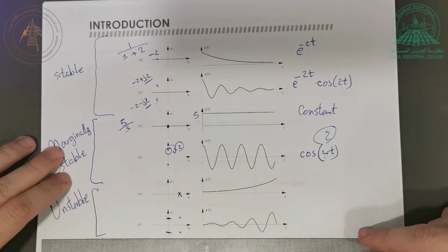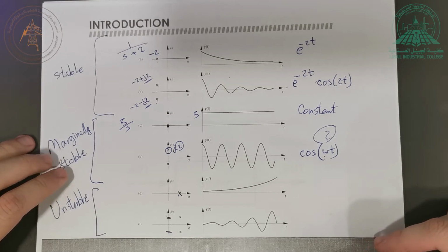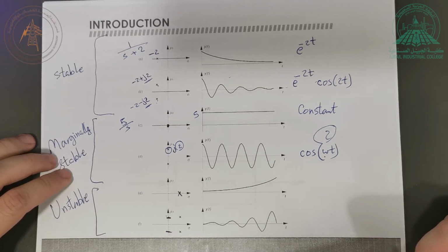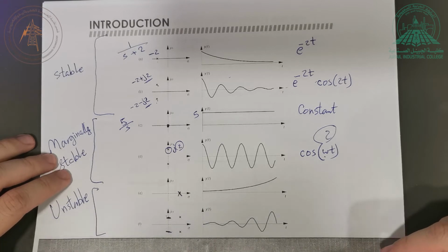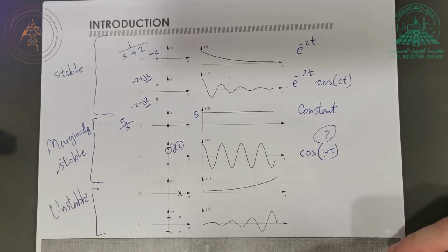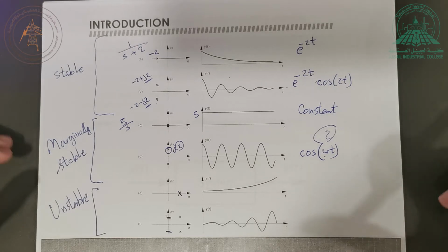Instability in power systems. For example, if you have several generators working in synchronism, and you have any fault, a short circuit at any point in the circuit, any type of fault, then if you don't clear these faults fast enough, the generators are going to become unstable and be driven out of synchronism. So the system is not going to be synchronized anymore.